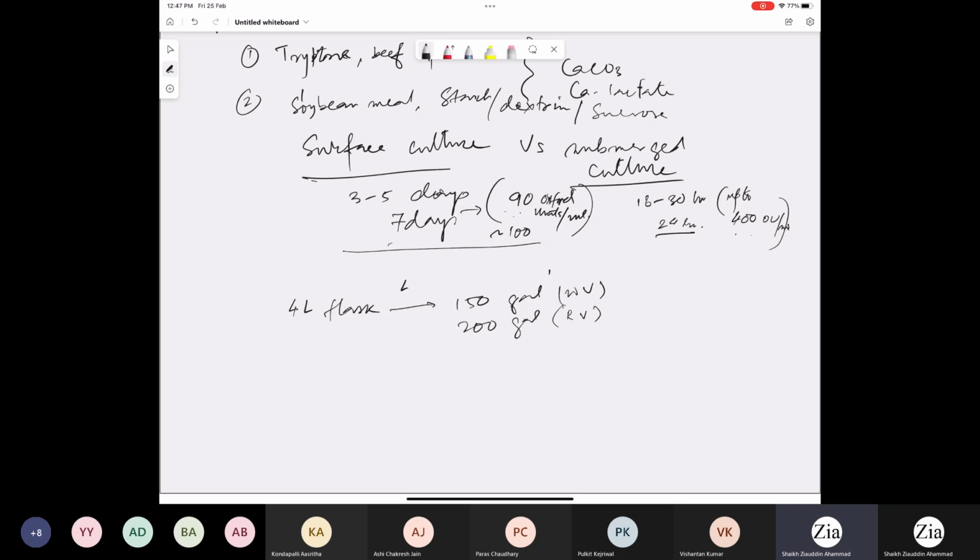So it will withstand this corrosive environment, and you do vigorous aeration. The entire process should be maintained at 37 degrees centigrade, and pH near neutral, around 7, and you continuously aerate to produce a sufficient amount of biomass.